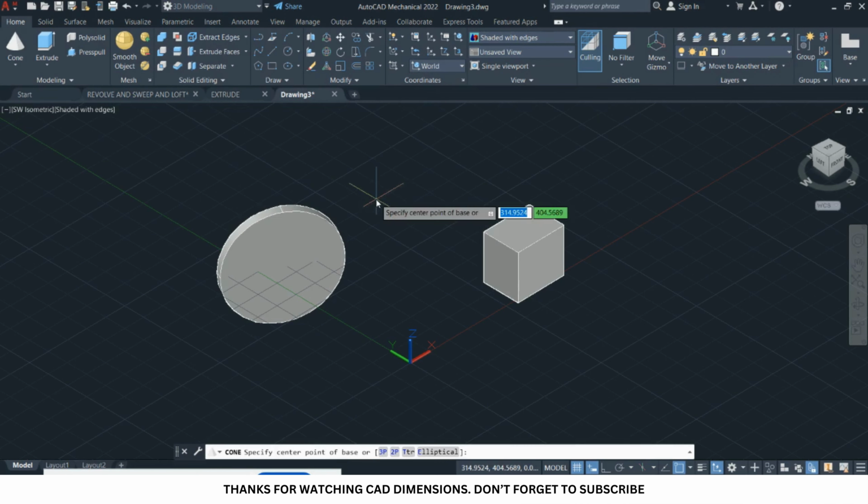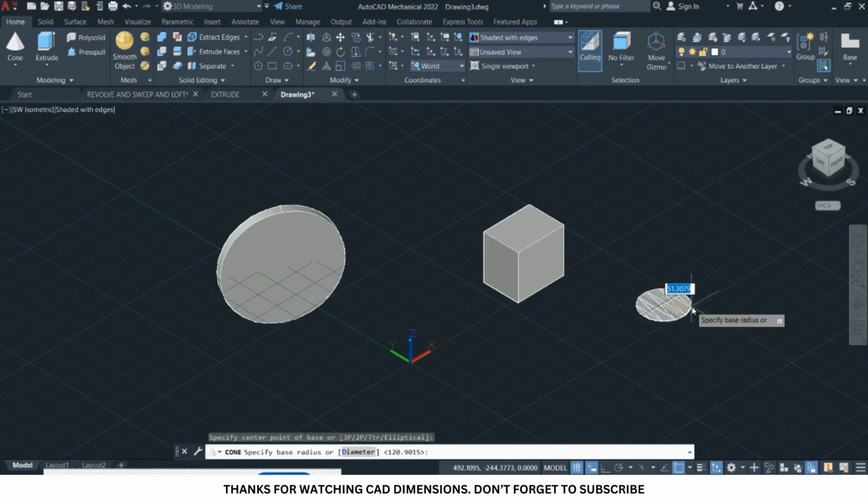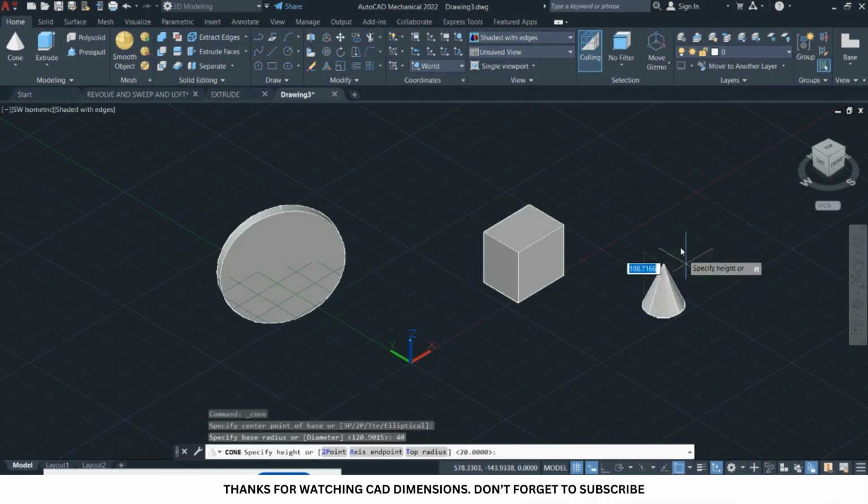Let's try cone. For the cone, yes, the same option. You specify your point, you enter the base of the cone, maybe 40, then I can now enter the height of the cone.